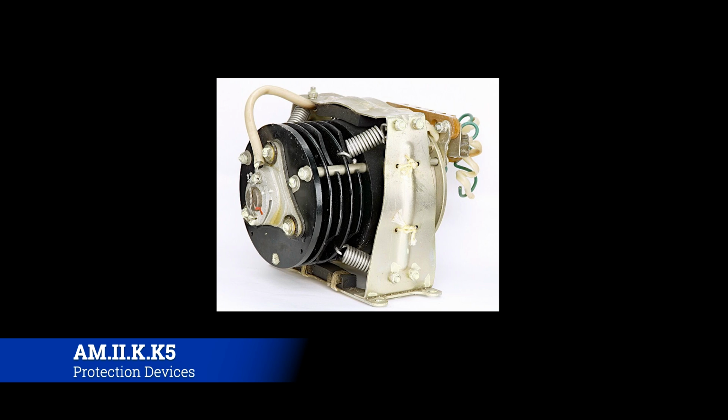All right, so let's talk about a couple of these voltage regulation devices. First is the carbon pile regulator. Carbon pile regulators control DC generator output by sending the field current through a stack of carbon discs, which you can kind of clearly see there. There are little black discs being held on by springs. The carbon discs are in series with the generator field, and if the resistance of the disc increases, the field current decreases and the generator output goes down. If the resistance of the disc decreases, the field current increases and the generator output goes up. So it's kind of a natural regulatory device. So that's a carbon pile.